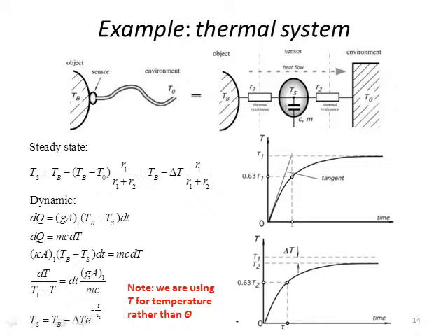It's always dependent on the material of the sensor and how well you can make contact. R1 is really the sensor head, and how well you can make a good thermal conduction path to minimize R1. If R1 ideally is 0, then Ts is going to equal TB. If R1 is quite large, then the temperature that the sensor tells you is TB is going to be quite erroneous.